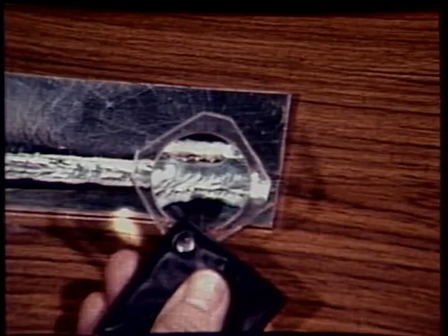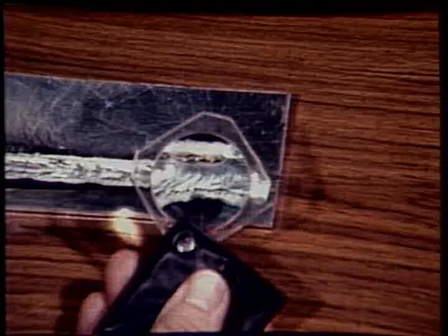The sensitivity of each method reflects its ability to respond to the size, shape, and location of discontinuities. For example, visual inspection is limited to discontinuities exposed to the surface, whereas radiographic inspection could be used to inspect both on and below the surface.